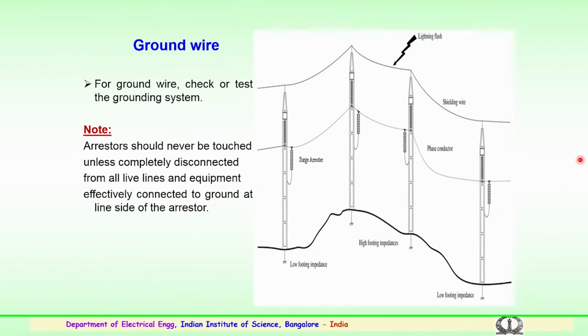The ground wire or the earthing wire plays a very important role in the substation. In case of lightning surges or lightning flashes, the proper shielding has to be done so that these surges are diverted to the ground without a rise in potential being seen by the other equipment which is connected. So, the earth wire or the ground wire is very important.